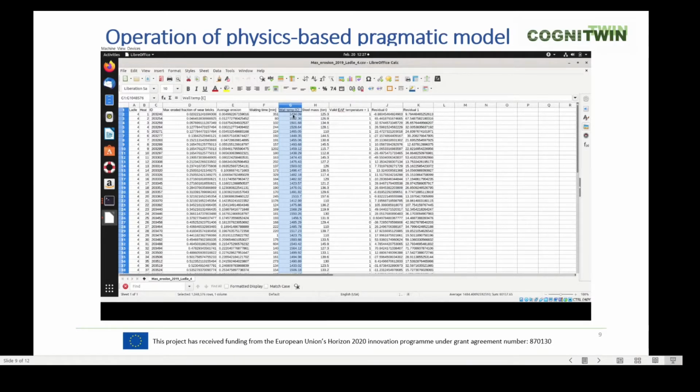So these are important numbers for making an assessment of this thermomechanical contribution to ladle erosion. But it's also important for the more classical mass transfer controlled erosion, because the temperature of the wall and the steel impacts solubilities and different kinetic contributions to the mass transfer and the refractory dissolution.